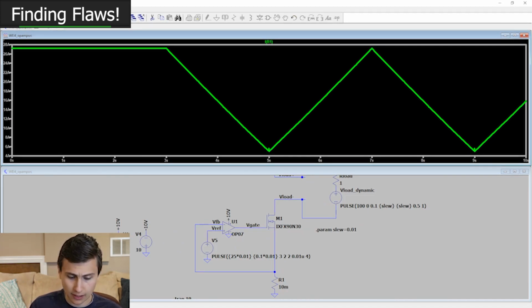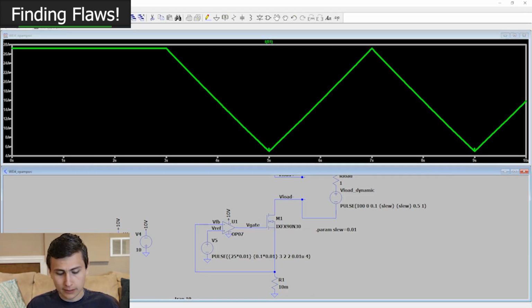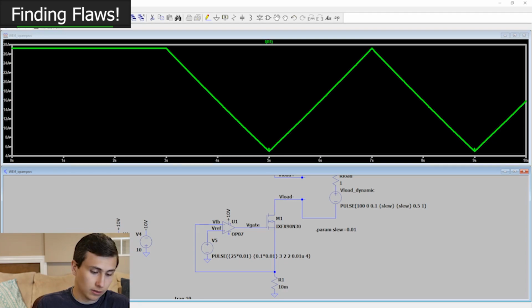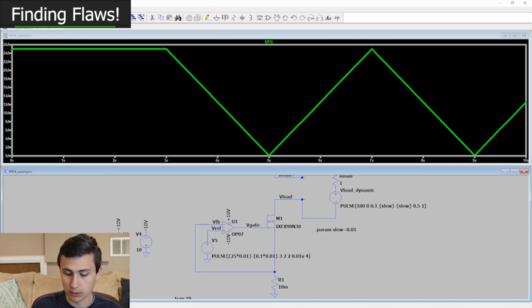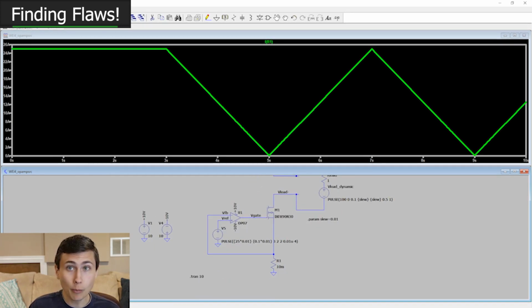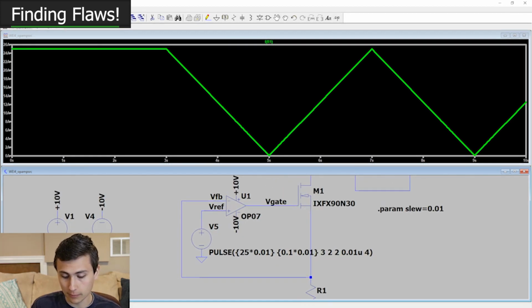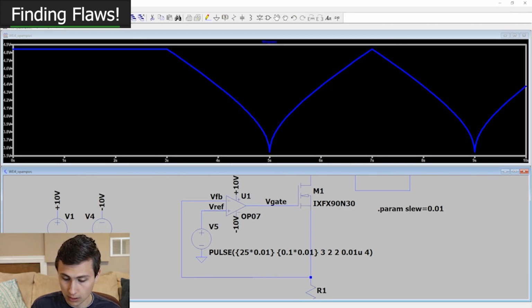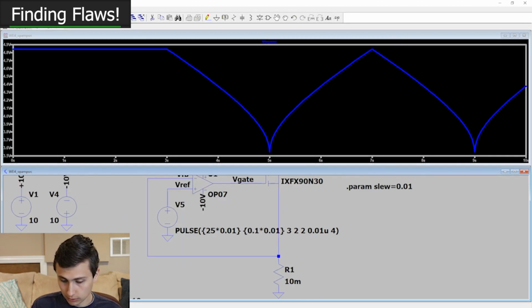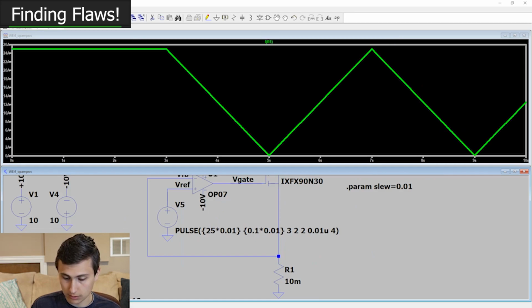As we're getting down towards this low end, this is where having that bipolar supply really starts to become important. Because as we're trying to drive the FET closer and closer to 0, the V out low starts to be an issue where we start to hit the lowest voltage that gate can get to. And since we're in the linear region of the FET, maybe we're just not getting a low enough output voltage to really accomplish that. And you can see just by adding that bipolar supply, just by opening up the MOSFET to go negative if it needs to,